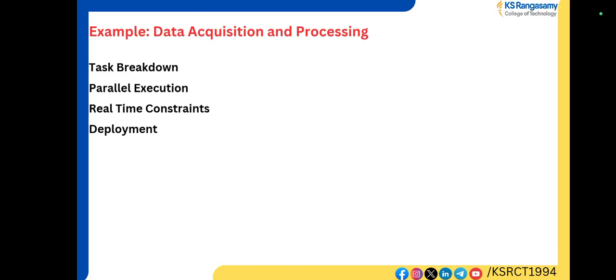Then parallel execution, we have to run each and every task that we have identified with a separate timed loop or parallel loop structures in LabVIEW. So while doing this, we have to ensure that tasks can communicate through queues to pass data safely between acquisition, processing, as well as data logging, as well as reporting. We have to ensure the real-time constraints,